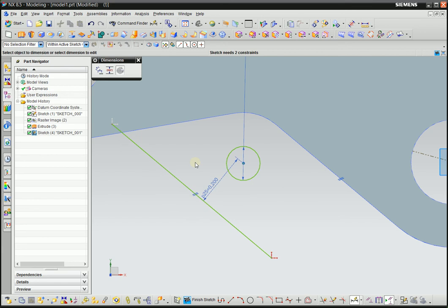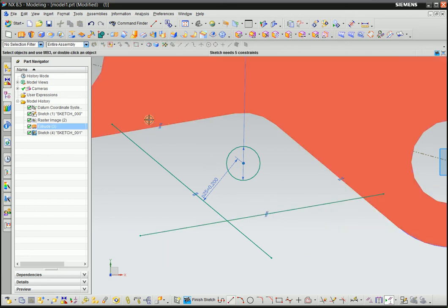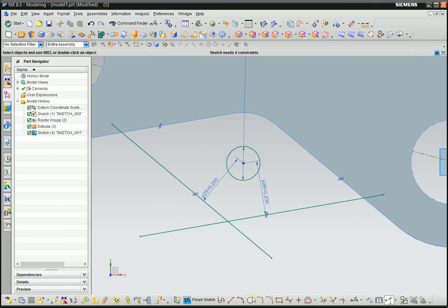You can keep track of the distance between these two lines, and then later we're gonna draw another line into that, also parallel, and just to be neat, can put point 2 to make sure these two lines are at the same distance to the hole. And next thing is fillet. You can fillet this too.